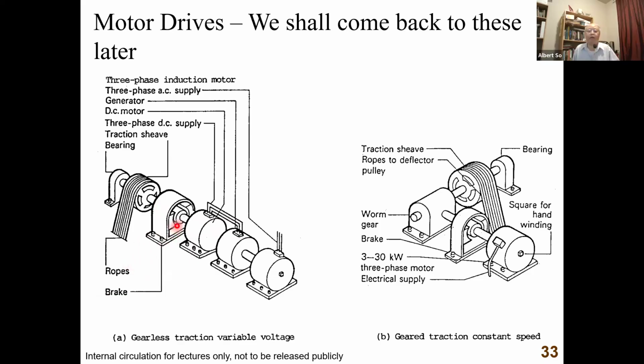And then during emergency or when the car goes to a floor, the motor stops operating and the brake is applied by removing the current. Okay, mechanically applied. And this we call a fail-safe design. Fail-safe means even if it fails, it's safe. No power failure safe.